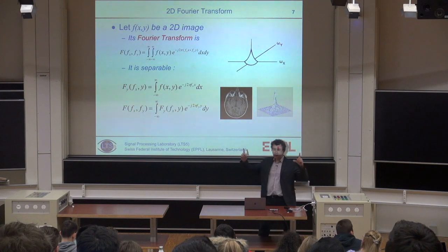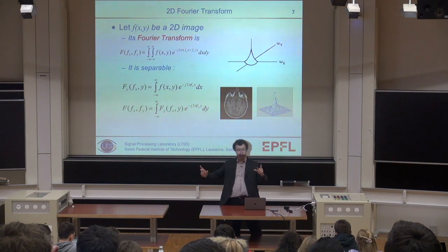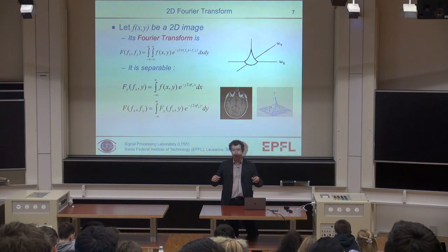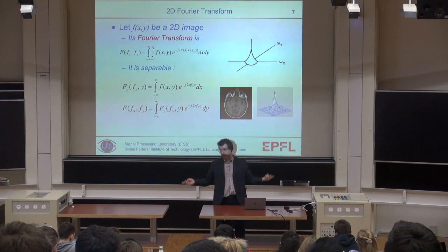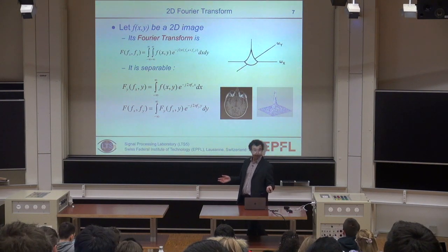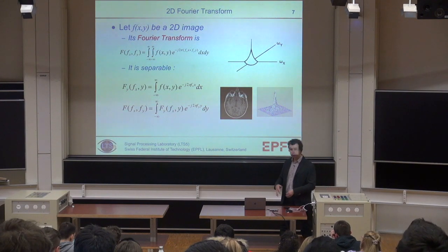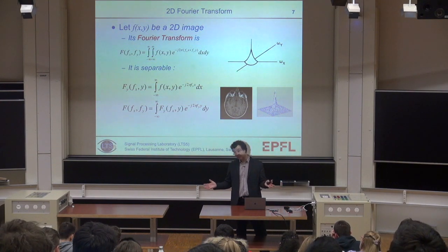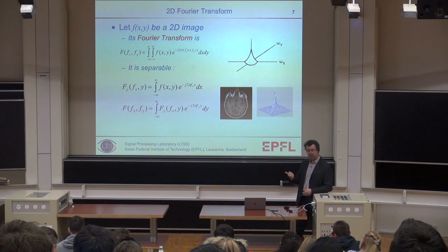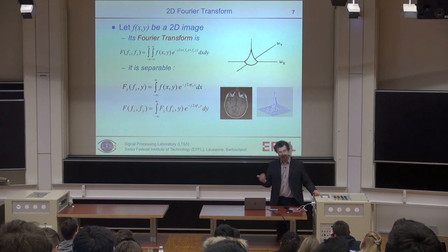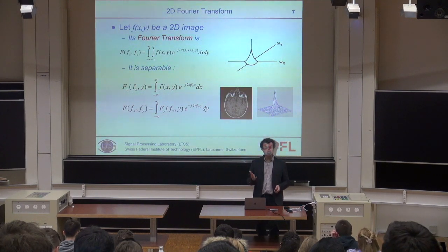We are talking about taking a picture of a real scene, so going from an analog world to a digital world, to a sampled world. We take a picture, and even if you have a super fancy, expensive camera, it is a digital image that samples reality. So we are talking about sampling, and sampling means sampling frequency, it means Shannon's theorem, it might mean aliasing, recouvrement de spectre, and this is the same in images. And we always have to keep in mind that there is nothing different between a 1D and a 2D signal in terms of sampling. You have the same risks. You need to take care of how you sample.